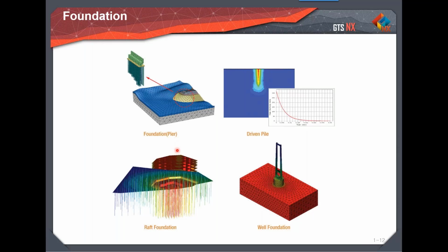This software can be applied to foundations, ranging from shallow foundations to deep foundations, and even dealing with the complex pile driven foundation. Since you were talking about the validation of the results, in order to calibrate the model before the start of your real project, you can always do the driven pile test in the software, so that you can calibrate your inputs and then proceed with the real project study. You can do such calibration, followed by shallow or deep foundations, ranging to complex pile driven foundations as well as caisson foundations. You can do all such kinds of analysis in this software.